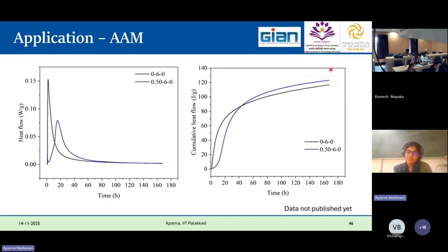This says that, again, your total compressive strength can increase. In the TGA curves also, we have seen there is an increase in weight loss. Here we have seen there is an increase in heat flow. These two are now confirming the hypothesis that although the retarder has been added, the total amount of hydration has increased with the addition of retarder.